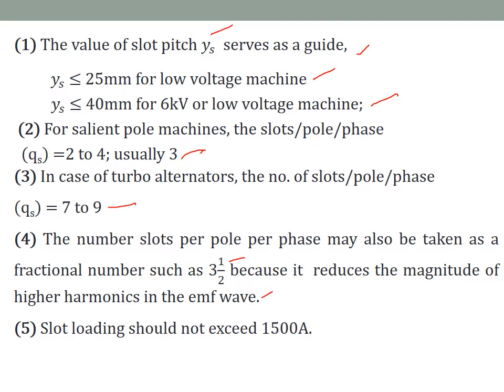Another guideline: the slot loading should not exceed 1500 amps. Slot loading means the number of conductors multiplied by the current in the conductors.